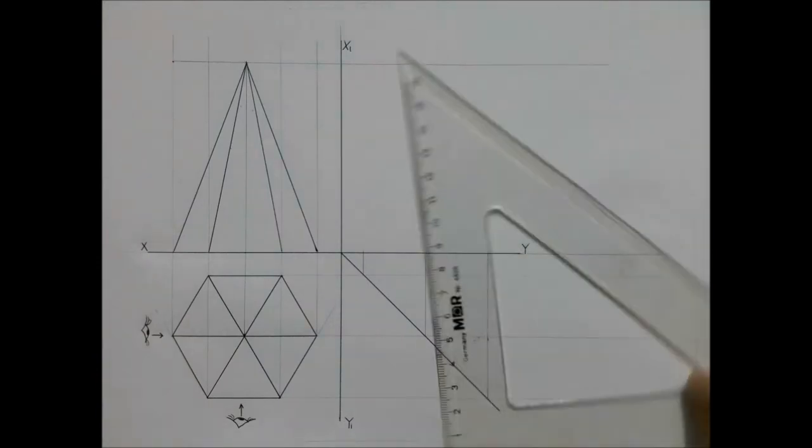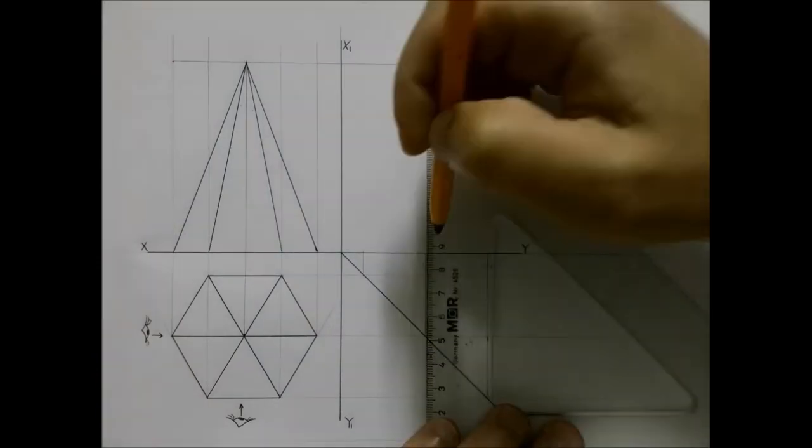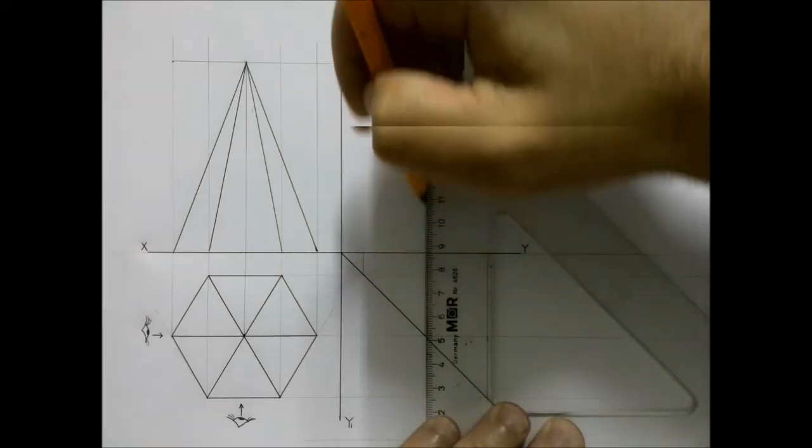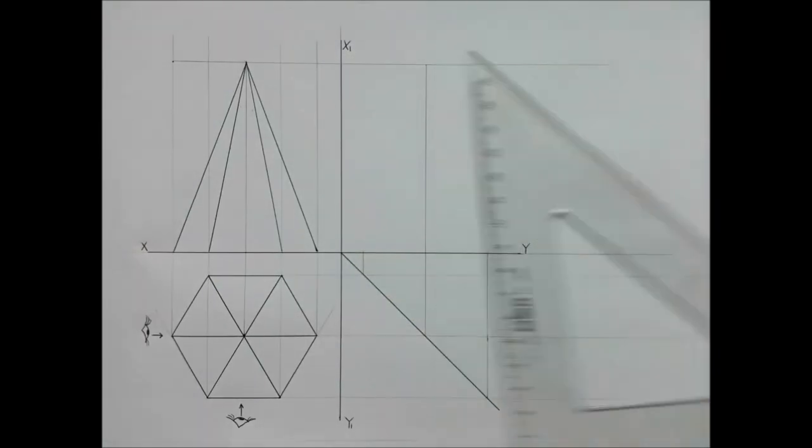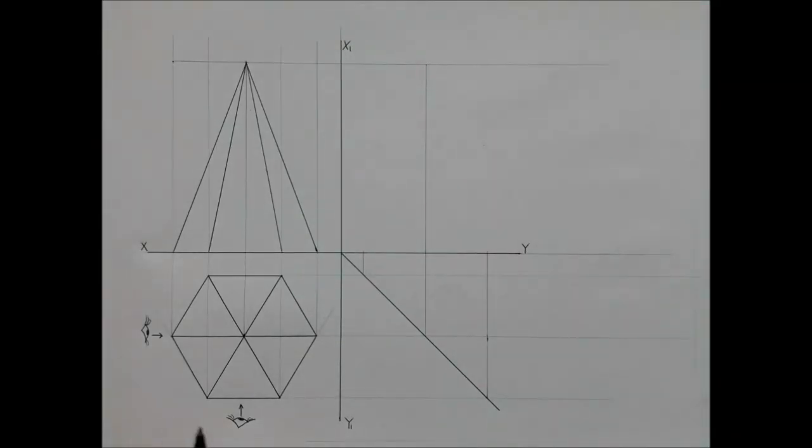Got the height, I can now go project the height over there. Very, very important. You'll note, yet again, from this side, I'm going to be able to see 1, 2, 3 surfaces, which proves correct when I look at my front view. 1, 2, 3 surfaces.